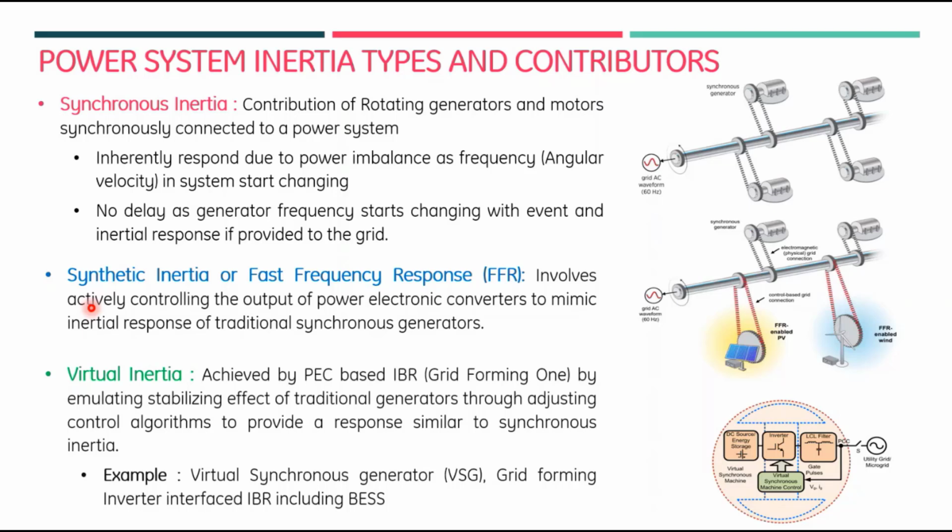So they are entirely dependent on the system frequency. If there is a problem with the voltage, or any transient in the voltage where they are connected, it will certainly impact the fast frequency response also. So that's why these are slightly delayed. They are not inherent. They are slightly delayed so that they get a very stable kind of voltage.